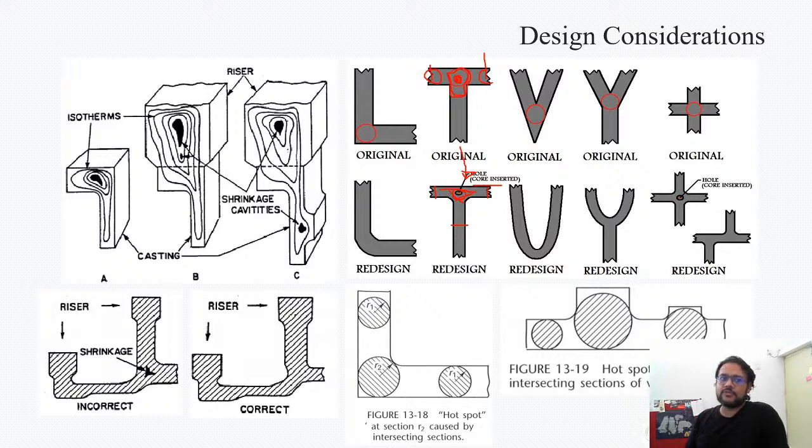Similarly, one of the thumb rules based on this is that you would try to put in large curves wherever possible. Instead of these sharp angles, sharp transitions, you would always have a gradual transition. That way you would not have these large areas where a large amount of molten material is accumulated, but rather a flowy kind of design where the material would flow from one end to the other, and that is what is being highlighted in this slide.